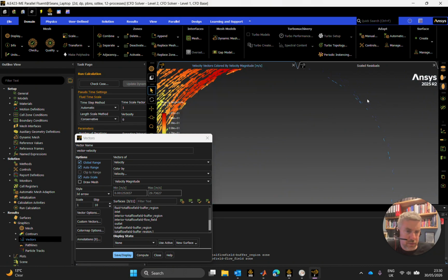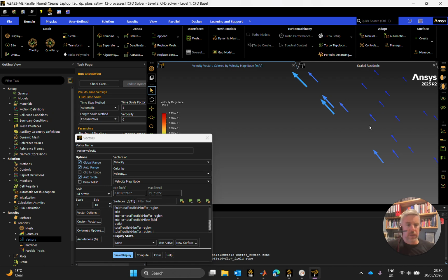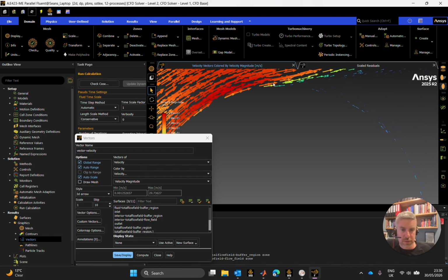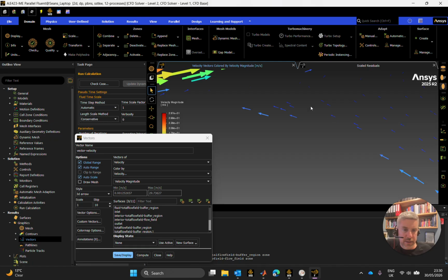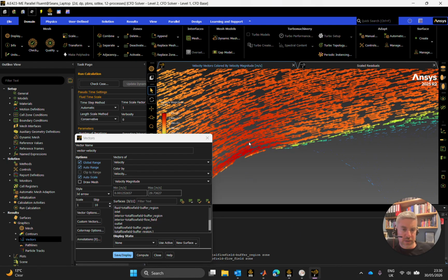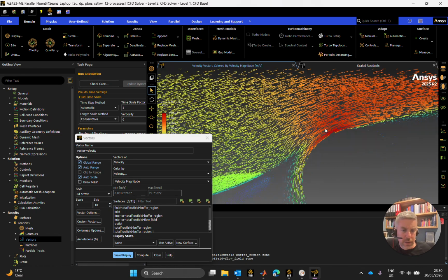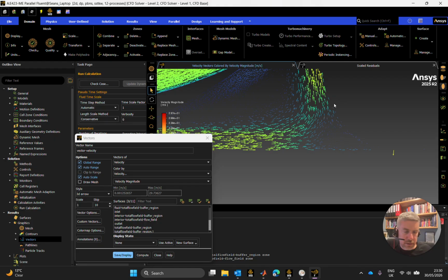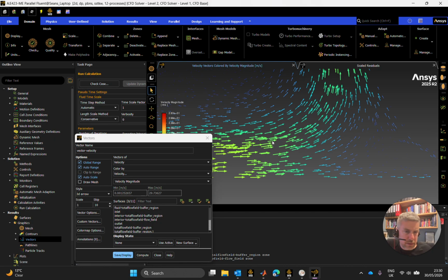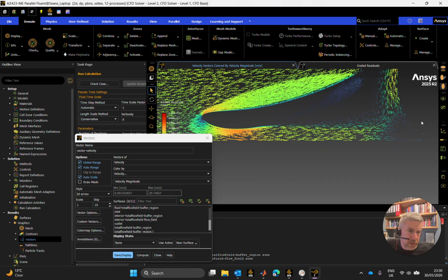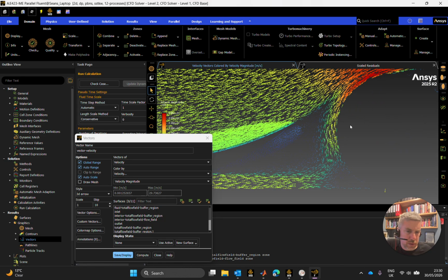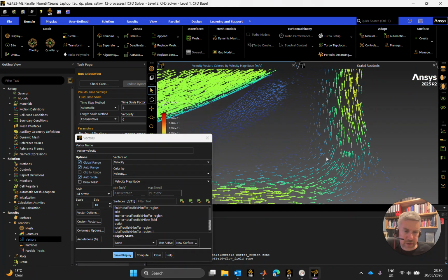tire. If we look to the rear of the tire, we could see the tire pulling air up, or pulling some flow up with it as it scoots around, and that then is obviously being overcome very quickly by the faster, higher energy moving air this way. Down here at the bottom, yes, regardless of what you might think, apparently this wheel could be pulling air down and into the ground with it. It has nowhere to go, so it's coming into kind of a dead region.